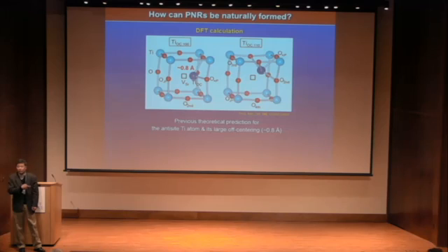The TE measurement is done with a top electrode, strontium ruthenate on top, and bottom electrode strontium ruthenate. Yeah, I understand. But did you measure the tunnel electroresistance with this top electrode? Yes, we did. It's very similar to barium titanate. We see the tunnel resistance, down state and up state, with very similar behavior to barium titanate. And the thickness dependence is very similar. But actually, it only works for thin ones because tunneling works only in thin regions. We cannot make thick ones.